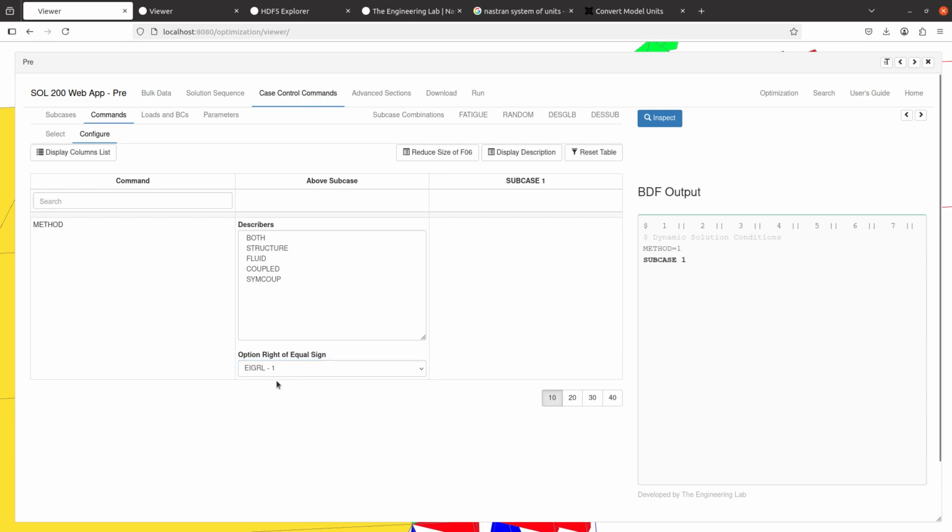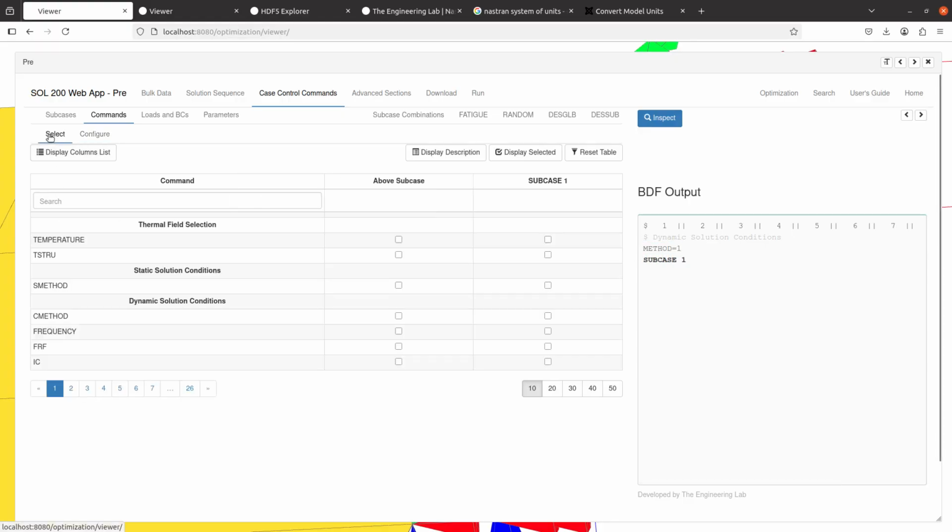So remember, the eigenvalue entry, we configured it so it extracts natural frequencies between 10 and 2000 hertz. Here, what we're saying is, Nastran, use this entry for the normal modes analysis. I'm telling Nastran to extract natural frequencies between 10 hertz and 2000 hertz. Next, let's go ahead and output some eigenvectors. So there are 2 ways you can do this.